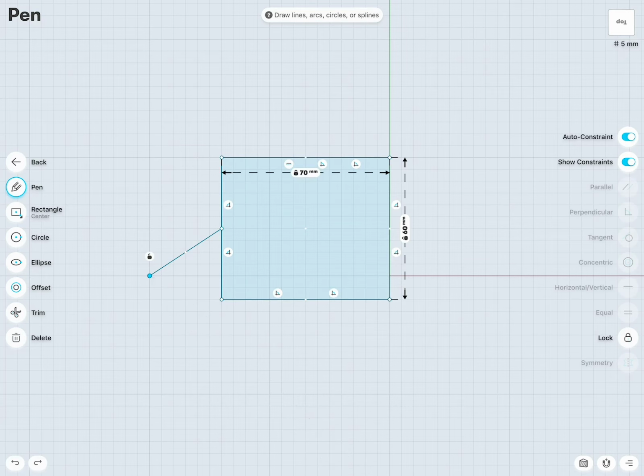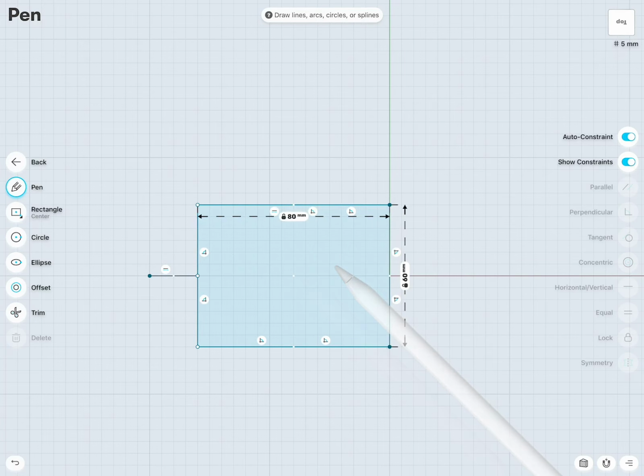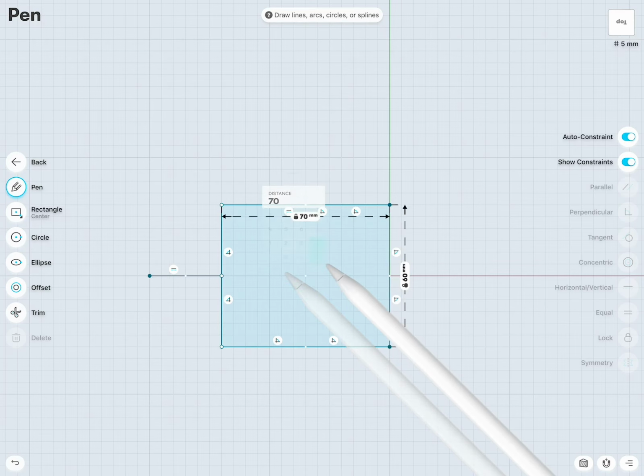So this point I select, lock it, then I can select this line and say be horizontally constrained, and that pulls the geometry down and everything now is locked. Very good. I could also prevent this rectangle to further move, so these 2 points I could lock. Now the only thing left is I could adjust, for example, the length. Very nice.